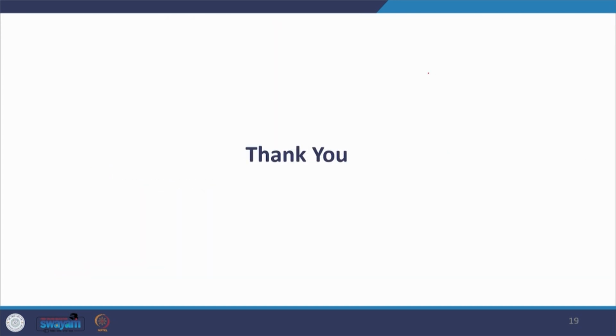So, in this class we have discussed the different components of numerical or digital relays. We have seen that there are various units or components of digital relays, and we started with the signal conditioning block, then we discussed the conversion subsystem block, then the algorithm part, then the digital input and digital output modules, and then the communication peripherals along with the human machine interface. And we have also discussed why all these subcomponents inside the digital or numerical relays are very important. Thank you.